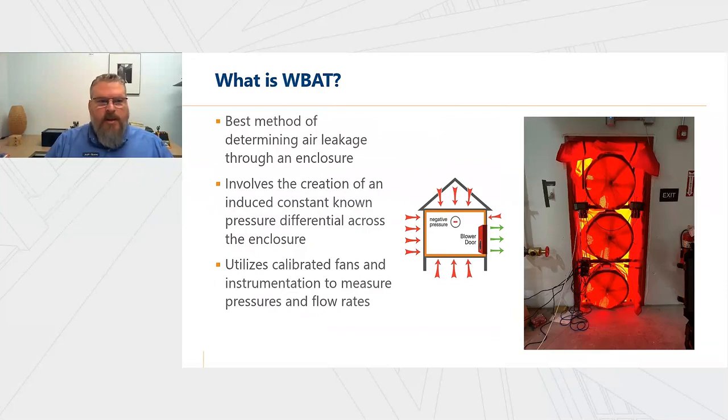So Bill talked a little bit about what it is, but in terms of what it is from an operational standpoint, first of all, it's the best method we have of determining a quantitative air leakage number that's repeatable and comparable to other buildings to know how the air barrier is actually performing. It involves the creation of a constant known pressure differential across the enclosure. With commercial testing, we're going to do this at multiple pressures in order to gain greater accuracy and tune out some of the noise from wind and stack effect and other things that can have an effect on the measurements.